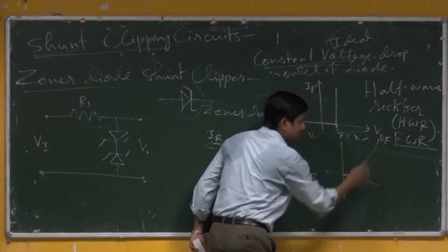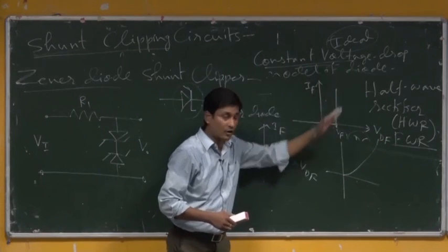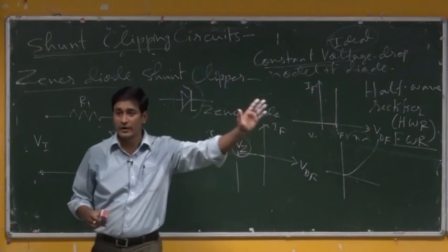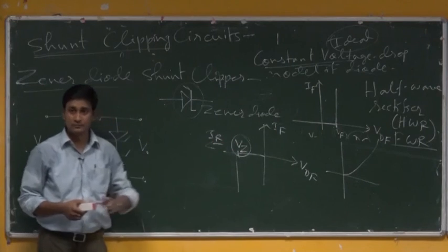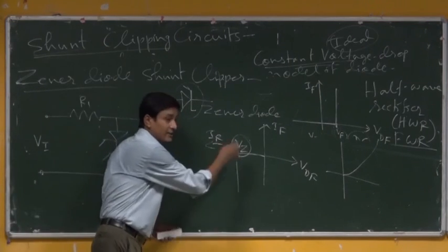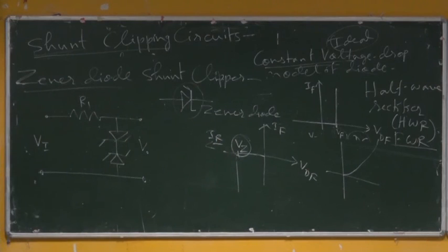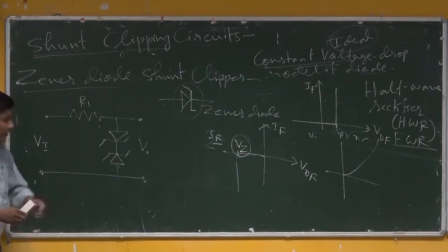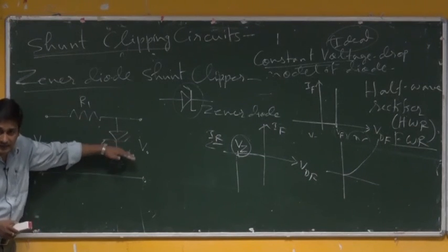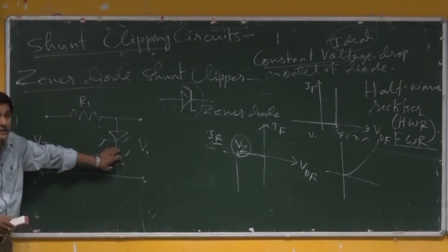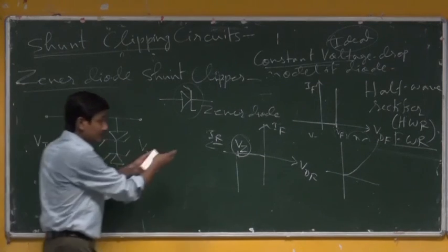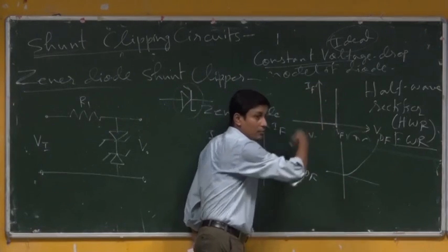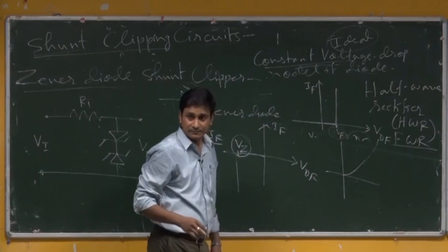If you consider it, the forward characteristic does not go so sharply; it always has a particular way of going where the current does not increase so rapidly, which a Zener diode can do. But the only thing is that it works in the reverse direction. So, in the discussions we have made, the only change here is that when you are considering the conduction of the diodes, you have to consider whether the Zener diode has reverse breakdown or not. So, what about the forward? With the ideal constant voltage drop model, some VF exists there, which is quite obvious.